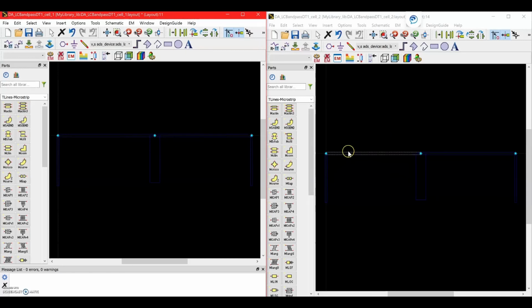And the nice thing with ADS is that you don't even have to use just these basic microstrip lines that we designed here. There are a lot of ways you can incorporate some of the bow tie microstrip lines that we've seen around. You can also incorporate these bends as well. Lots of ways you can solve this problem.